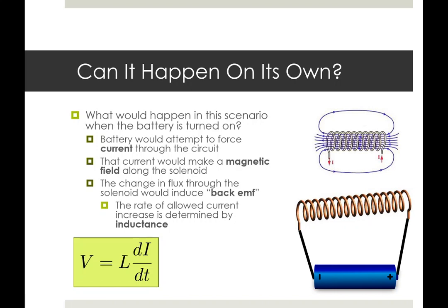Now, what you're seeing here is basically an application of Faraday's law. It's saying the voltage is the time derivative of the flux, where we have done some Biot-Savart calculation to relate current to flux here, and we've reassigned the derivative through there. Now, that is a complicated calculation, but we can treat this definition of what we call inductance like another relationship, like Ohm's law, V equals IR, and the capacitance definition of Q equals CV, as just a ratio, where Ohm's law is the ratio of how much voltage you apply to how much current you get out.